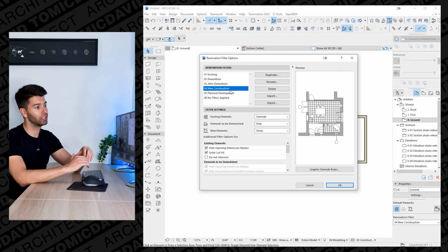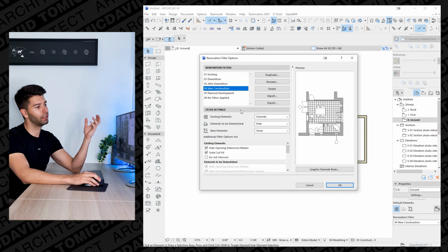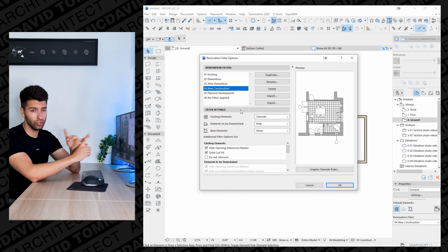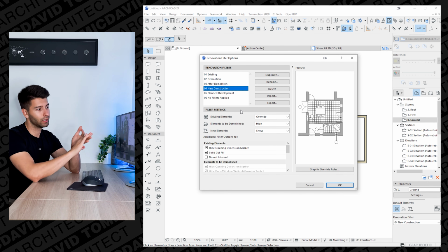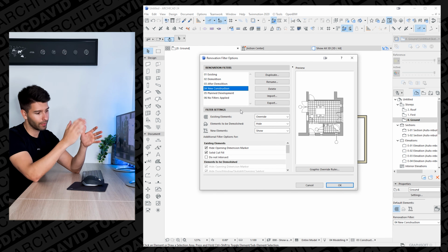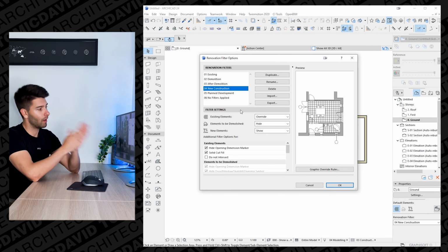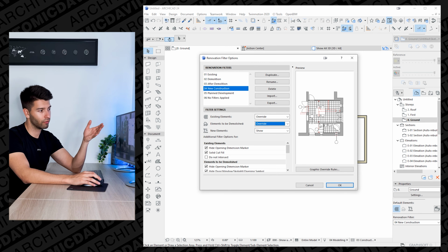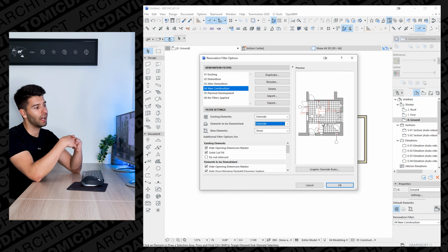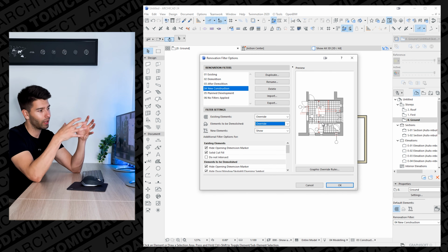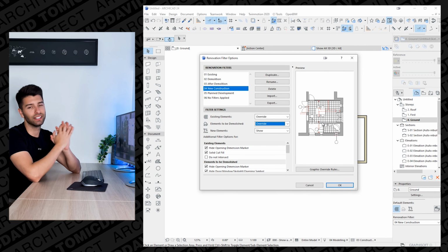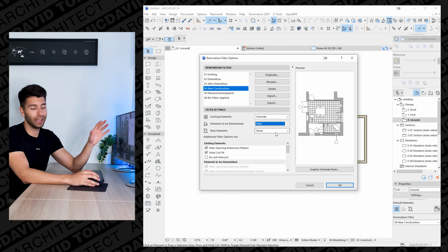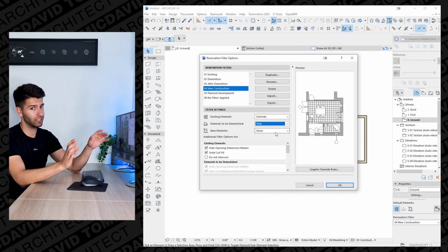Finally, new construction is of course the most important. It's the things that we can clearly differentiate between the old and the new, and we know exactly where those old things are gone simply by flicking through those pages. I personally don't show any of the information from the demolition plan. For example, if we were to override and show everything demolished on one plan, it would be very messy, very clunky and hard to read. So we simply hide everything demolished, in my opinion at least.